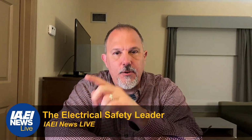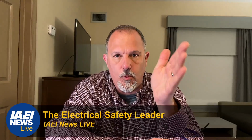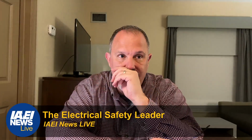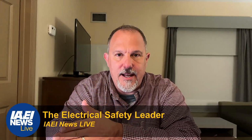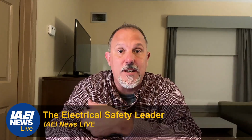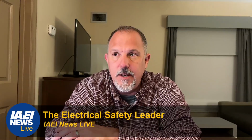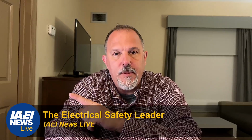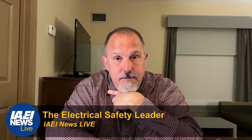What we're trying to get to is, if you kill power, if you establish an electrically safe work condition, say that you have a panel board and say it's an HVAC piece of equipment, and the HVAC equipment has to have a maintenance receptacle. If I kill power to the HVAC equipment, I don't want to also kill power to the receptacle, because that's where I'm going to be using that receptacle for drills, etc. So that receptacle cannot be fed by the same circuit breaker that feeds the equipment that I'm trying to maintain.